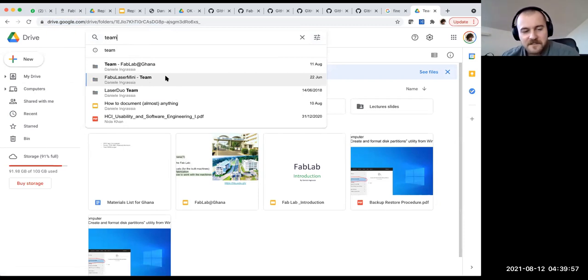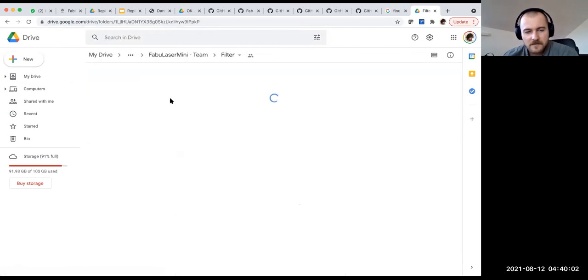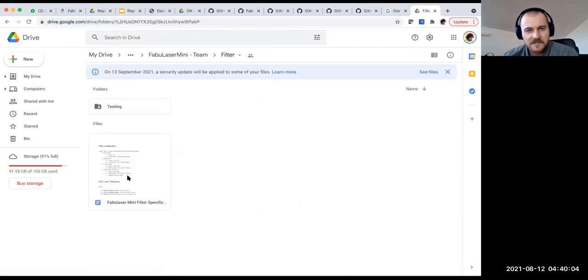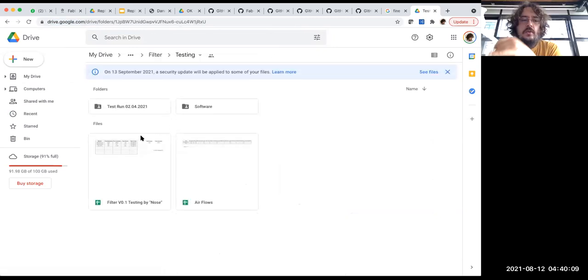I remember with these sensors, with different gases, you get different results. And what was your result in terms of measuring? So you have to know that you have to calibrate these sensors beforehand, and there's a complex algorithm that was written in MATLAB for doing that, and then translated to microcontroller code, to Arduino language. And we have pre-calibrated these sensors, and we have let this sensor run for 1 day without gases in our environment, just to create the right offset between the situation with the gases.